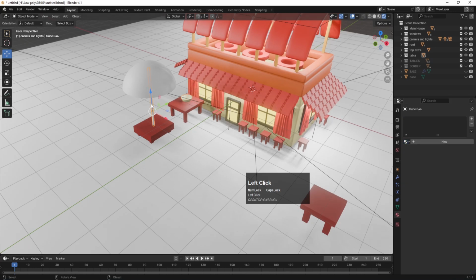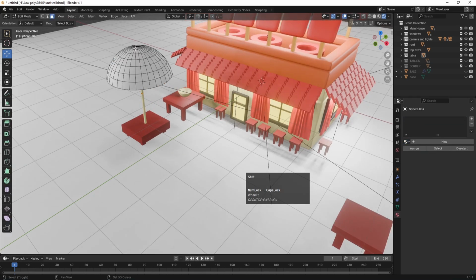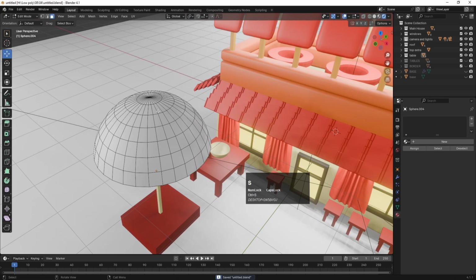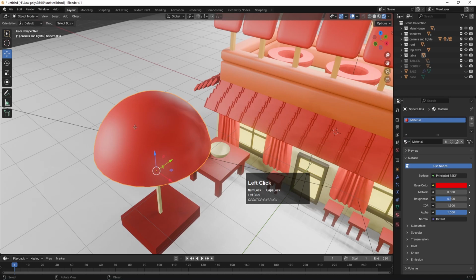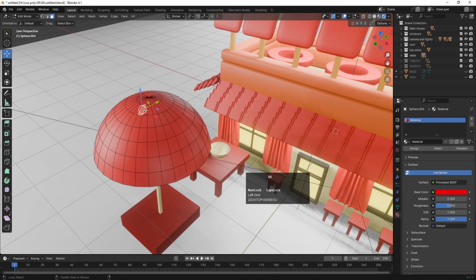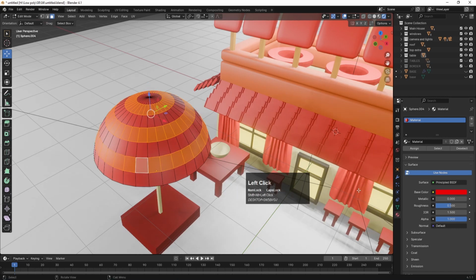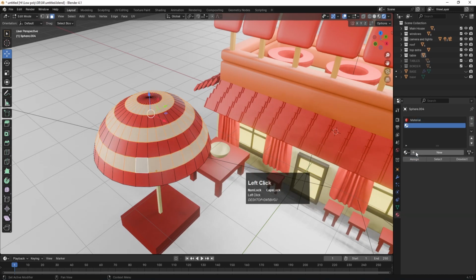For this one, first you can apply this house color as well to give a window like structure. For this one, I'm going to again create this house material, and for this one go to the tab over here, and let's try to create some different colors. So first of all, initially let's select this, and we will apply this red color over here, then go to the tab. Then by holding alt, I'm going to select these faces. By holding shift, make sure to select faces like this, and then create a new material, first assign and new.